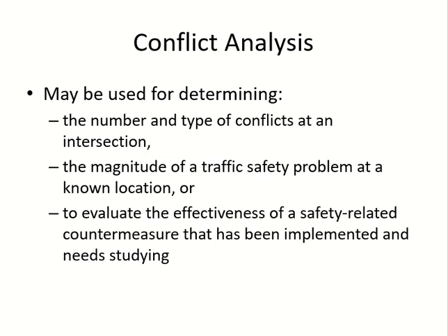So most of the conflicts are happening between the vehicles, rear end. One vehicle stops suddenly and the other vehicle has to stop very fast. So most of the conflicts are this type, so you know what the problem is then. Or most of the conflicts are happening between right turning vehicles and vehicles which are coming from this direction. So based upon the type of conflict which is happening more commonly, you know the type of problem you have, and whether the problem is very serious or not. You can look at the type of conflict and know the problem you have.